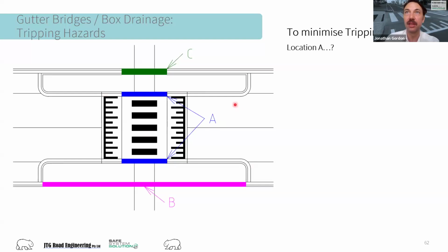For this scenario at location A, I'd suggest that you do the full width of the platform. If this was quite an extended platform, even, say, I'm presenting here a pretty standard Victorian one-way crossing with 4.5 meters across the top here. If this were a bus route, you might be extending that platform length more. I'd still suggest you go the full width, because the platform looks trafficable for foot traffic, and it would be unnecessary to cut this short just for the crossing itself.